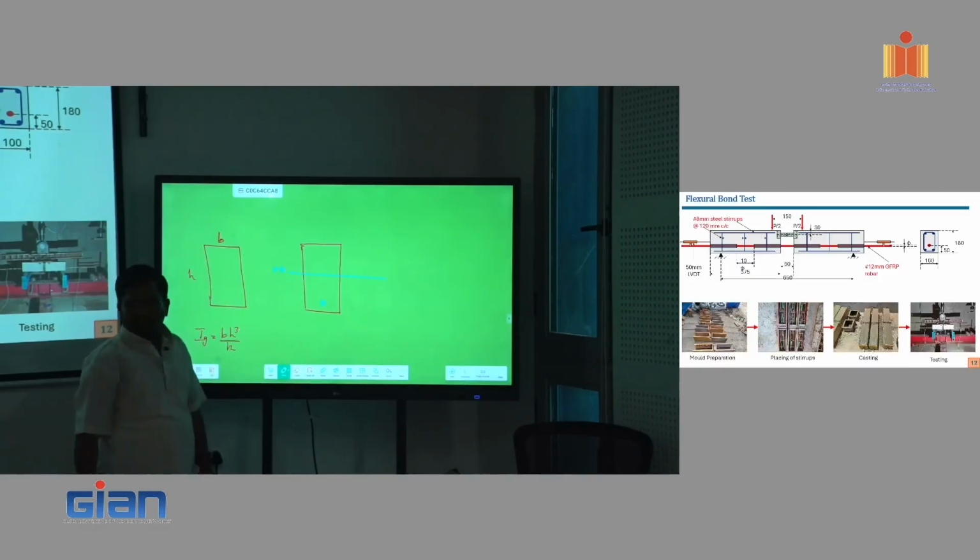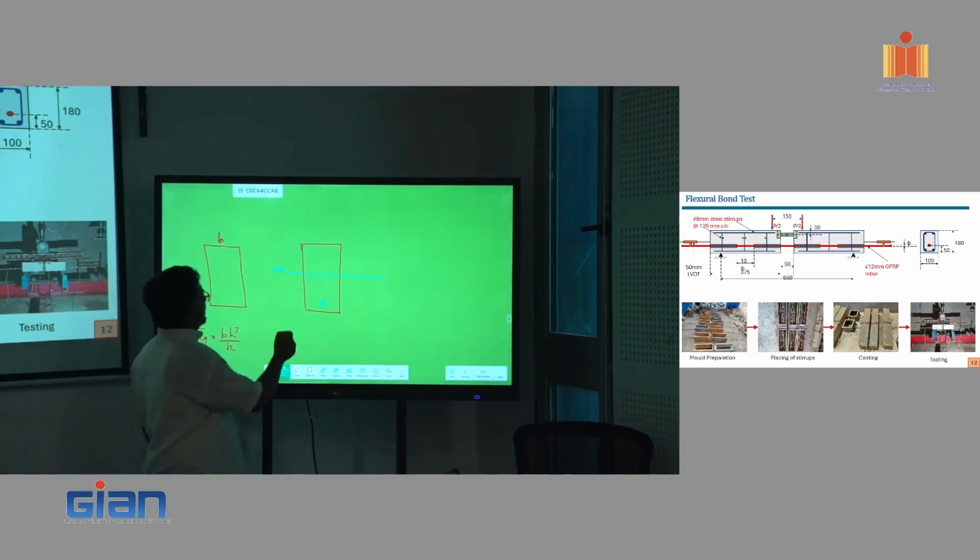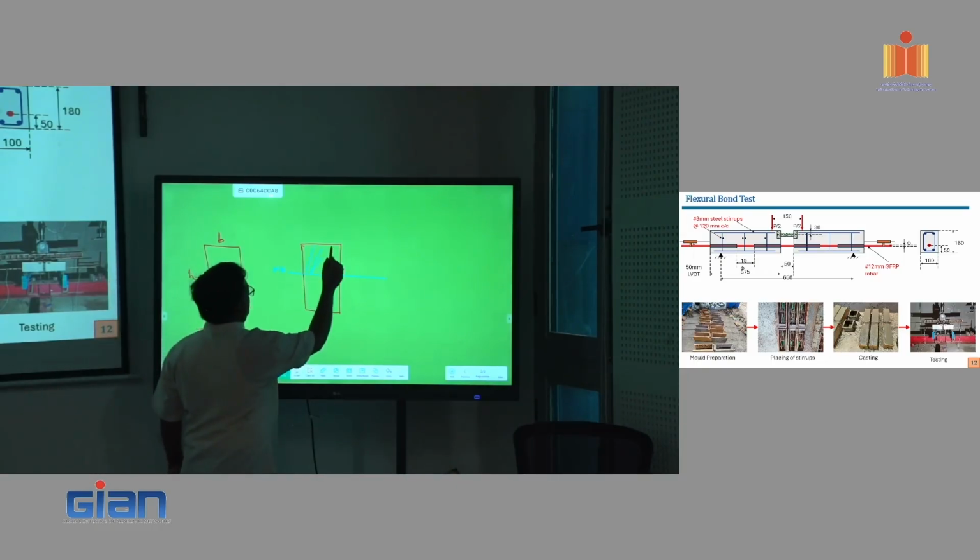Now what would be the moment of inertia? Let's say that at service load it is really cracked. I told you service loads are going to be 65% of ultimate. Typically cracking moment will be only like what we have seen, 10 to 20% of our ultimate. So definitely under service loads concrete beams will be cracked. But we design it to make sure that the crack widths are less, right? So this is your cracked section.